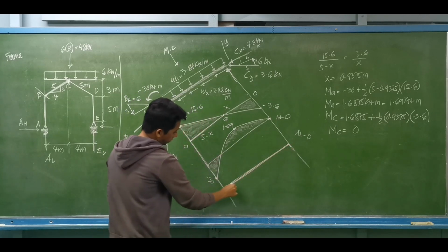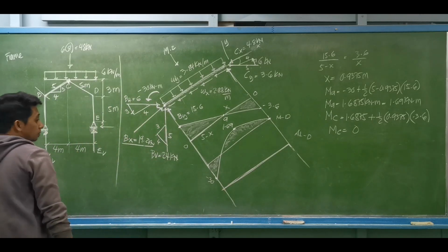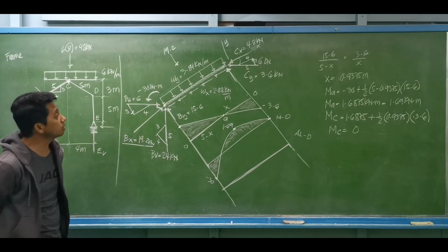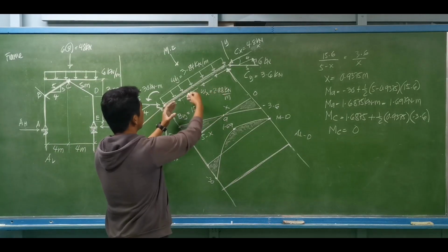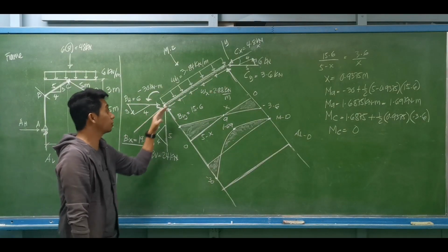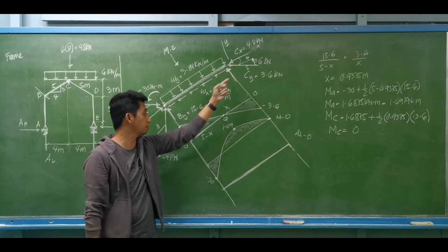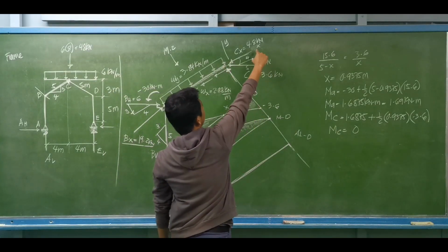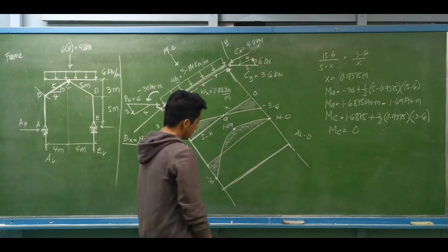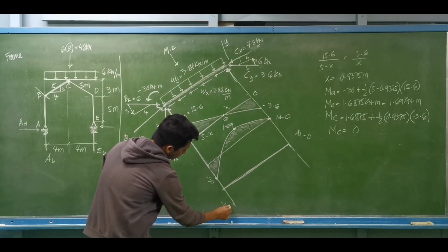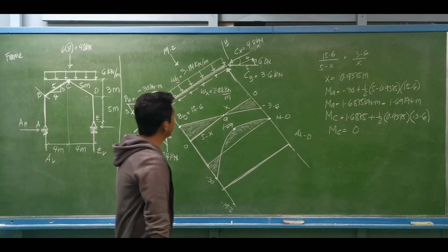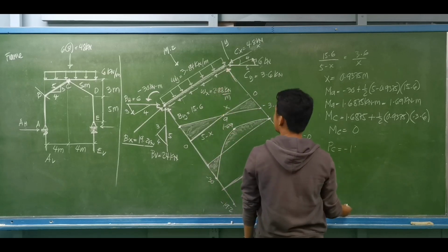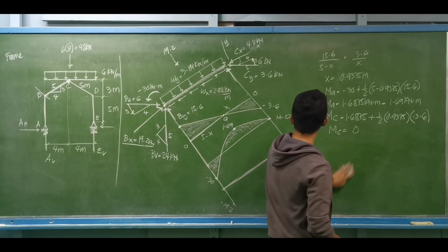Then for the axial load diagram, as you can see here, we have 19.2 kilonewtons that is compressing the member. All you have to do is match the downward or upward forces parallel to the member, or along the axis of the member. 19.2 should be equal to 2.88 times the span plus the component of this 6 kilonewtons, which is the 4.8. So we have to start here at negative 19.2. Let's say the axial force at C is equal to negative 19.2. I'll just do a check here.